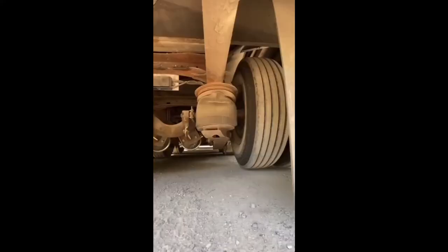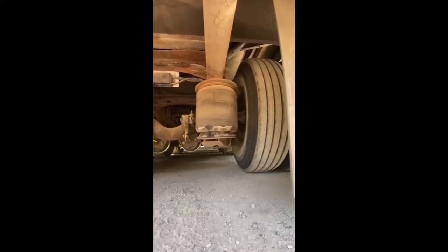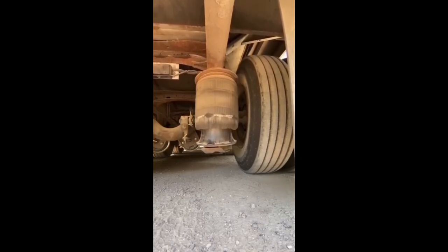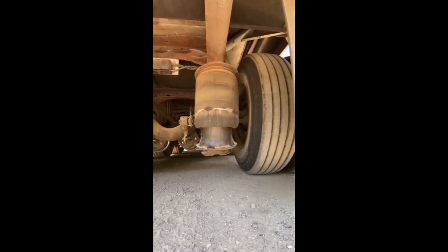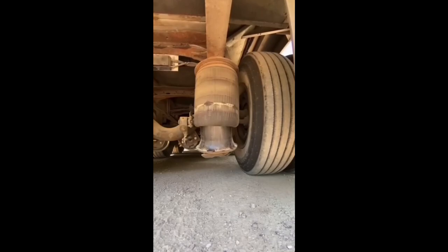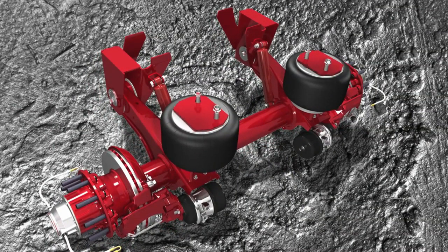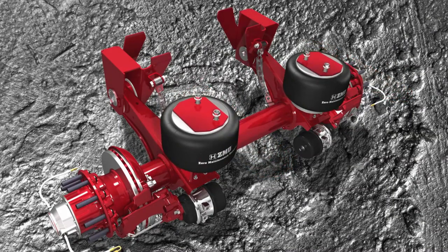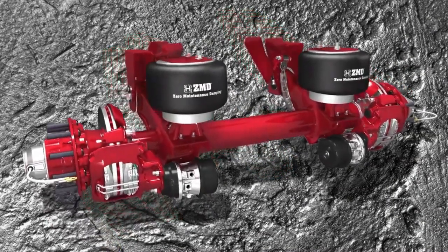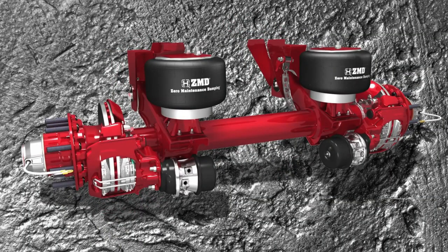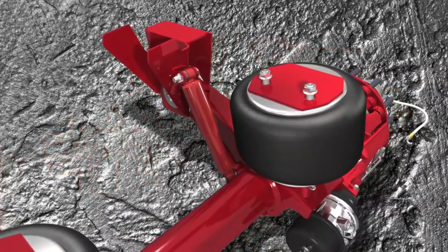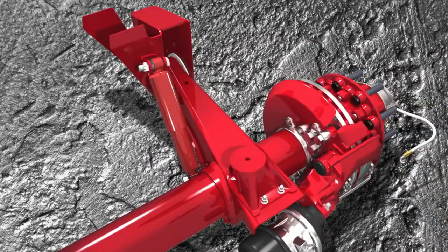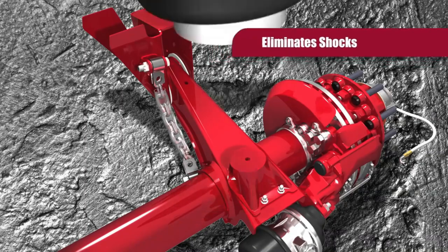Fourth is airbag. Airbags are essentially simple rubber components designed to contain and hold compressed air. They are often referred to as air bellows. There are different types of airbags, including piston type and elongated bellow type variants. These airbags leverage the compressive properties of both air and rubber to absorb vibrations and facilitate the adjustment of the vehicle's height, either raising or lowering it as needed. To achieve this, compressed air is introduced into the airbags, inflating them and subsequently altering the suspension height. Typically, these airbags are positioned between the vehicle's frame and its axles.